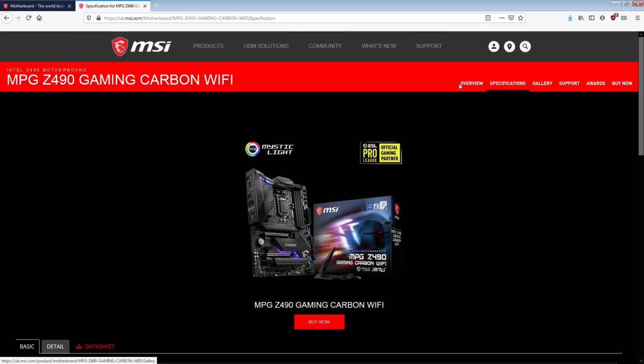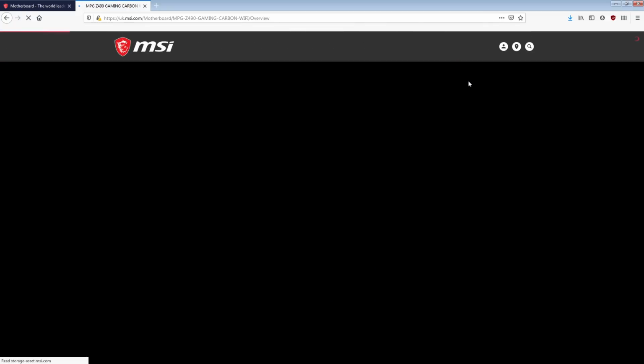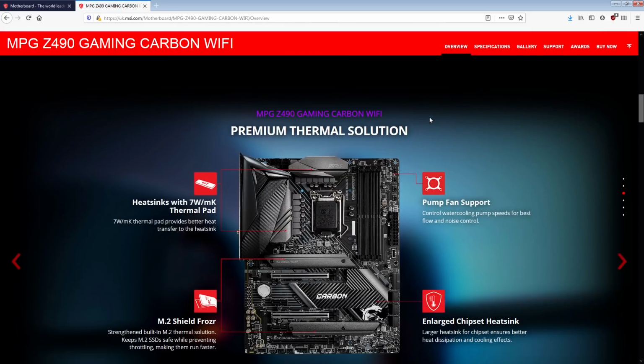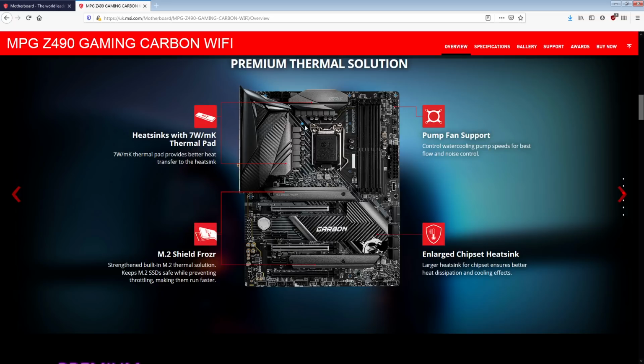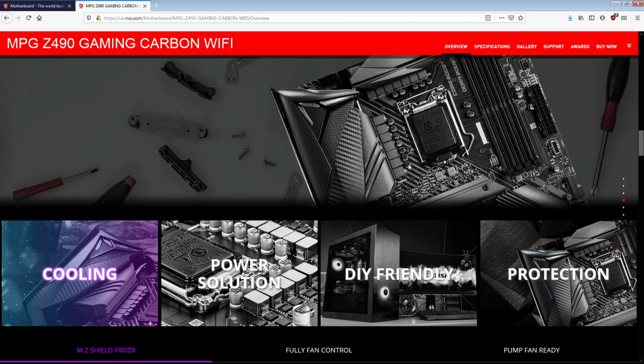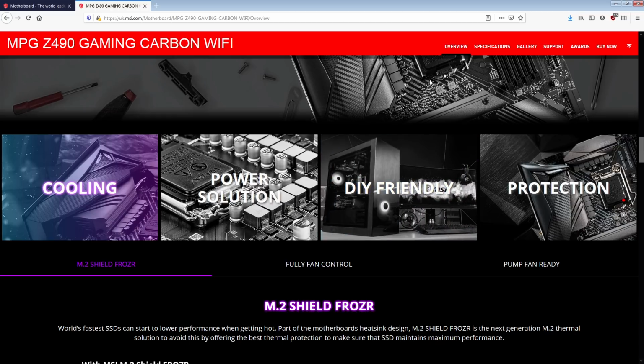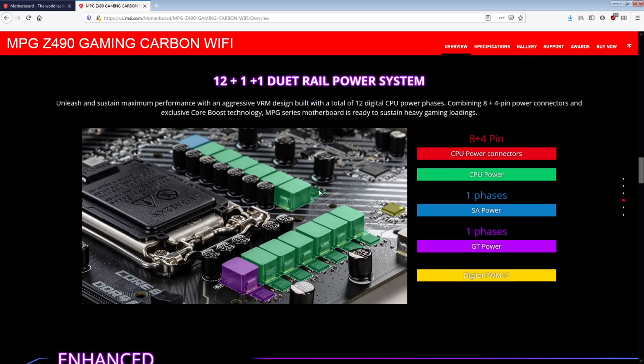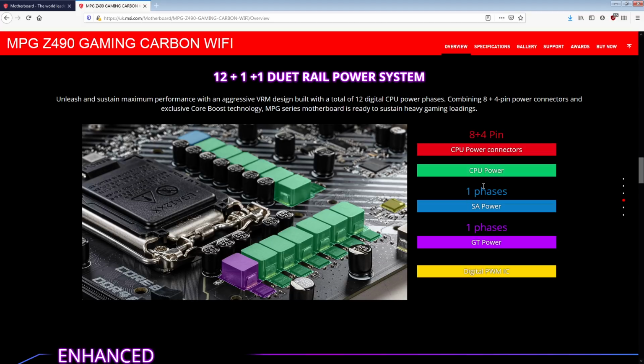So anyway, with this board, you get a solid VRM, but I think this is just a 12-phase, right? 1, 2, 3, because this is going to be VCCSA down here, so 1, 2, 3, 6, and then there's an iGPU phase. Actually, 2-phase iGPU maybe. Anyway, so this is going to be a 12-phase vCore. Wait a minute. Is this the wrong? Oh, no. Yeah, I am correct. 1-phase SA. 12, yeah, okay.